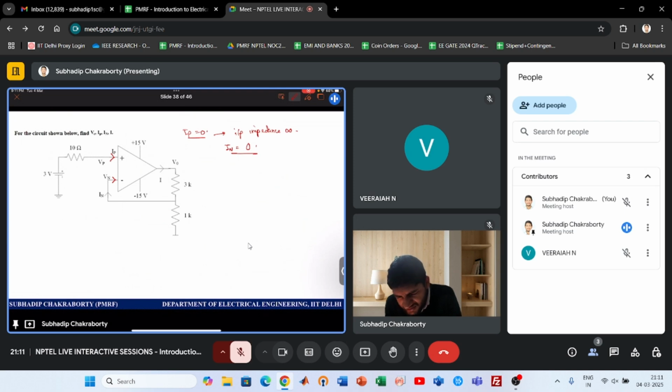So now let us talk about something about the voltage. Let us apply virtual short. Vp is equal to Vn, because the op-amp needs to be thought of as operating in the amplification zone. First you assume that the op-amp is not operating in saturation and try to find the output voltage. If the output voltage magnitude is less than Vsat, then it is okay. First apply virtual short, and now see Vp equal to Vn. Good.